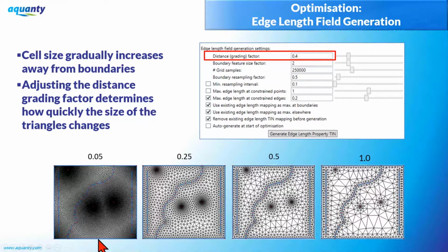So you can see here how this affects the overall density and quality of the triangles in our final mesh. Many but higher quality, aka more regularly shaped triangles on the left, and fewer but more irregularly shaped triangles on the right. The default value here is 0.4, which is usually a pretty decent trade-off between overall cell count and the quality of the triangles.